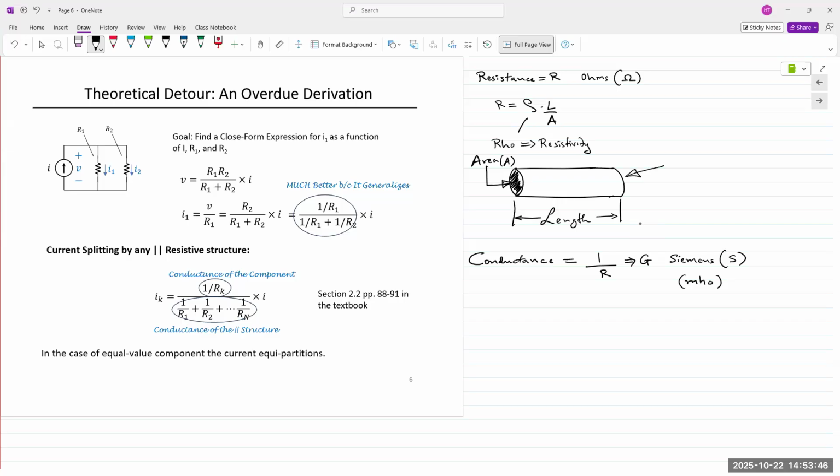So while North America uses 120 volts, most of the world uses 240 volts. This is the reason why. Instead of increasing the current, you increase the voltage and you send it over long distances, and you minimize your losses during transmission.